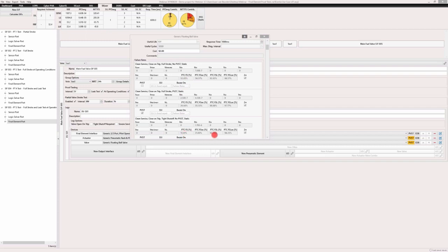If we do a leak test, however, you can see that the leak test will detect a lot of those seat failures. So actually the proof test coverage goes up compared to proof test coverage for the normal operation, because now there's more failures to detect. So obviously if we look at one device, a higher proof test coverage will be better, more extensive to test.